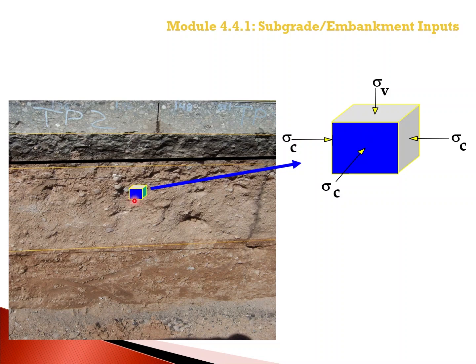In other words, each element of soil is confined due to the surrounding materials and also has a bulk stress and/or deviator stress from the overburden of whatever exists above the element of soil. This includes the vertical stress from the overburden materials and the lateral stress, based on the at-rest pressure coefficient to determine the lateral stress.